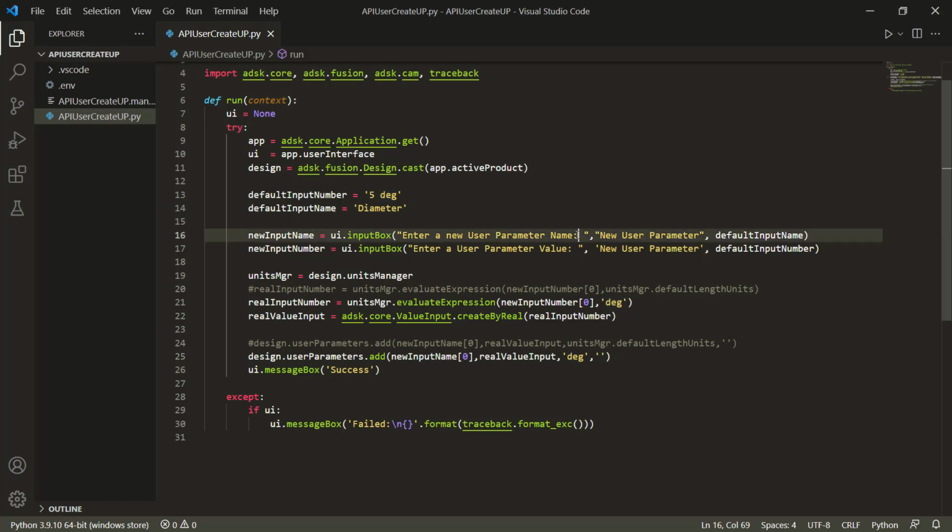Now keep in mind that with this user input, there is this default value, which is what we're pulling in. But remember that this is a tuple. It's passing back a string and the Boolean. We can do some work with the units manager and we can check if the units are valid. So if this is something that you want to continue to pursue, you can carry on going through the units manager property and see all the different calls or modules or functions that we can pull up. And then you can find out if one of those is going to help you do the conversion. But we're not going to go down that for this example. It's just going to get a little bit too detailed.